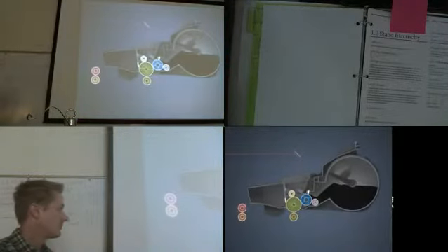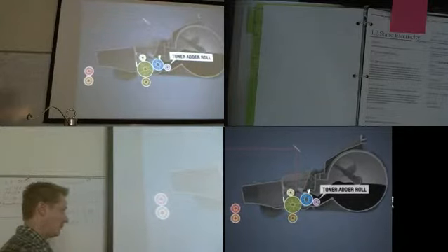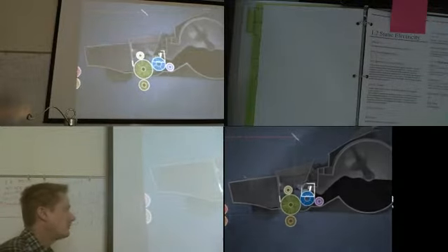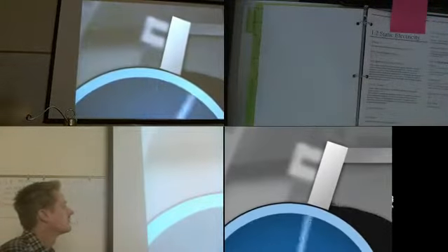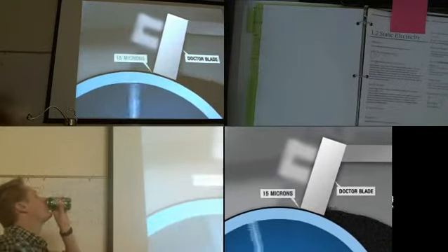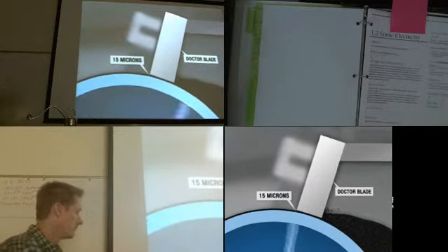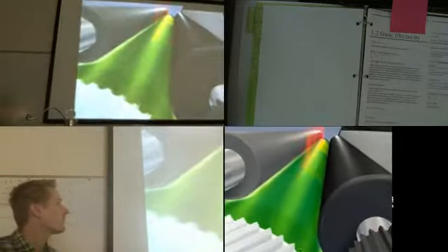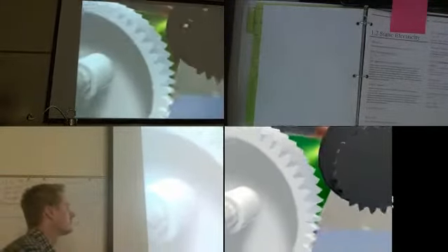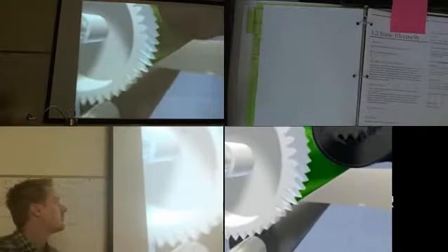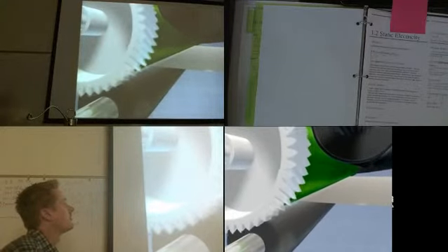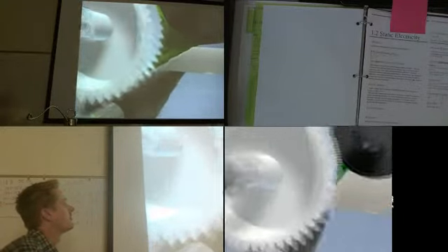Next, the image is developed. The toner adder roll coats the developer roll with toner while electrostatically charging the particles. As the toner is placed on the developer roll, a leveling device called a doctor blade evens the toner to a thickness of approximately 15 microns, just slightly thicker than a strand of silk. As the developer roll and photoconductor drum come into contact, the negatively charged toner is attracted to the discharged areas of the drum. When the paper passes under the drum, the transfer roller applies a slight electrical charge, causing the toner to move from the drum to the paper.